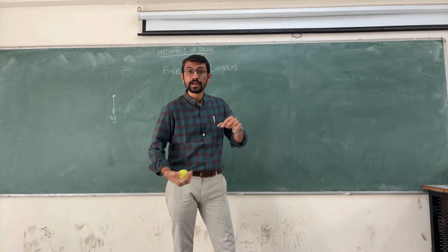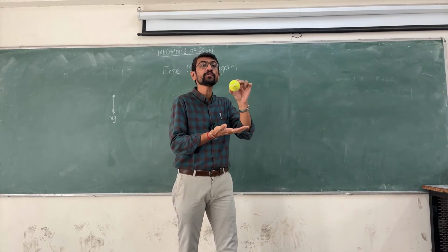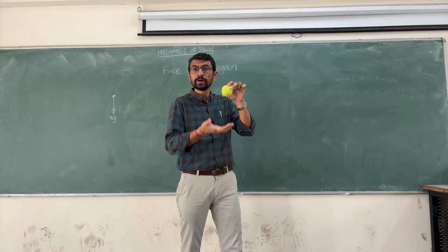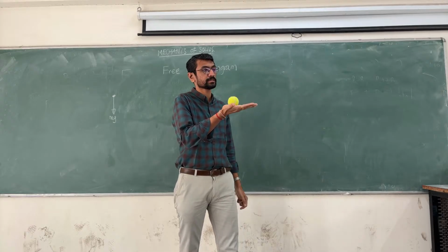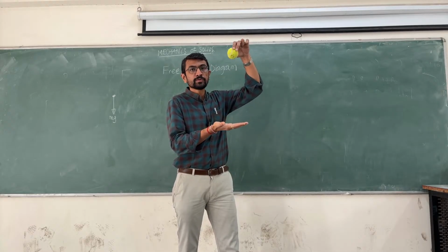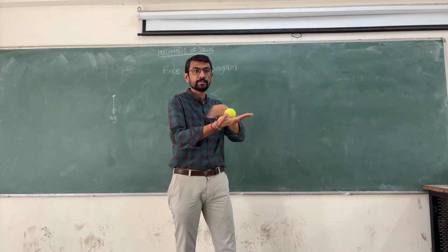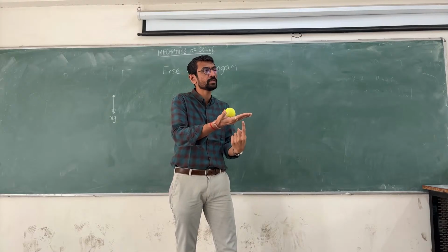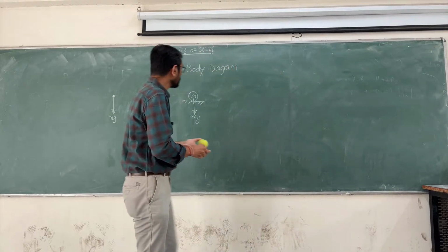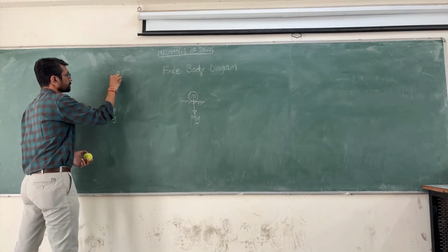Action is this, and when you are reacting to that, when you are opposing that force, because you want to keep this in equilibrium, so whatever is the final force acting on this material or body or particle, you have to resist that force, for which you are providing a resistance, a reaction. It means that W equal to mg is acting on it, and you are also providing W equal to mg. My hand mechanism is providing W equal to mg in the opposite direction to keep it balanced, to keep it in equilibrium. So the free body diagram of this mechanism is now, R is my reaction.